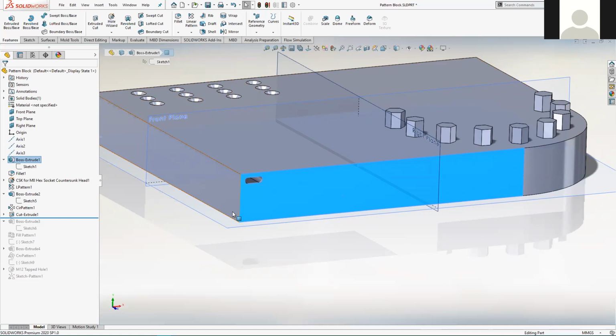So it can copy them in a sort of honeycomb style. So I think if you set the copy angle at 60 degrees from each copy, you get copies that arrange themselves in that sort of stacked hexagonal style. And there's various other types, but let's get it up and running. So I've just made sure I've not got anything pre-selected. So you can see I had that face selected, it was highlighted in blue, and then to deselect I'm just clicking in some empty space over here. So make sure you've got nothing selected.